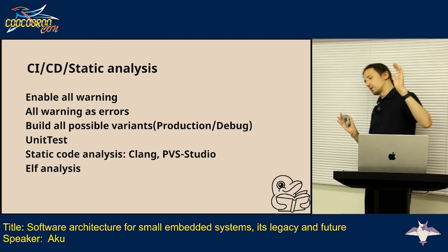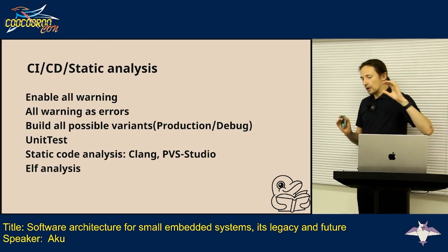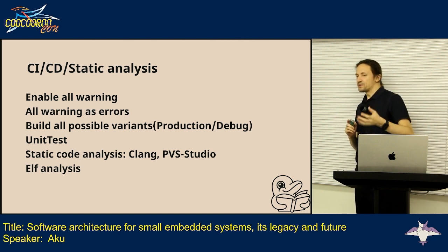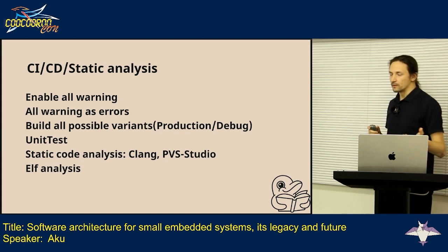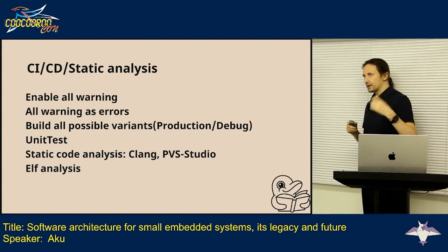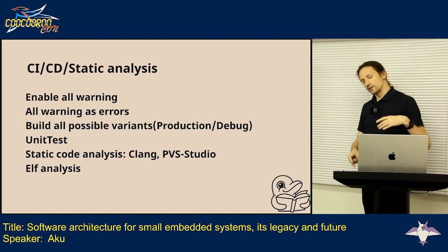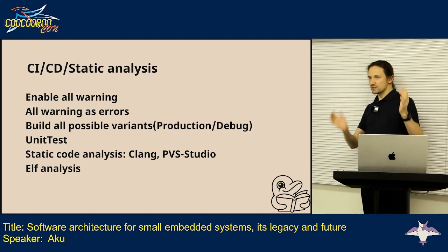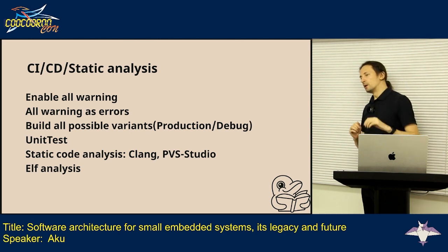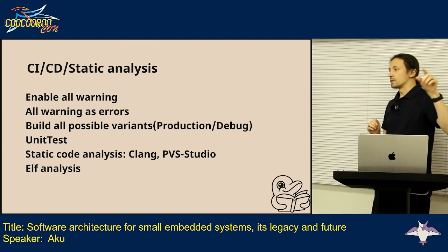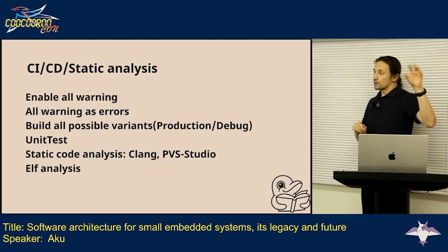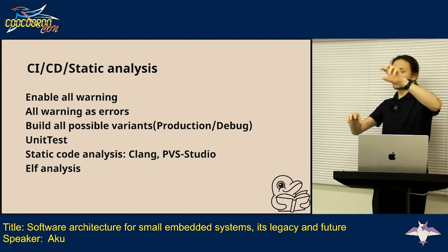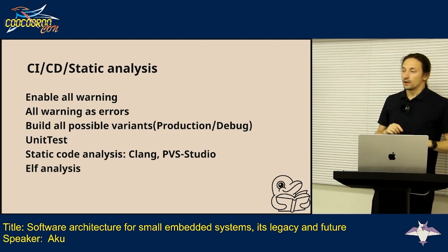And in addition, one of the things about small embedded systems is that you have RAM and you have flash, and you're writing in C. You're not writing in assembler anymore. And writing in C actually allows you to make a mistake. Just imagine you have constant data that you're not going to change, but this data must go into flash. And then you forgot the const expression at the beginning. So what will happen? This data actually will be placed in flash and then will be copied into RAM. And that's what you would like to avoid.